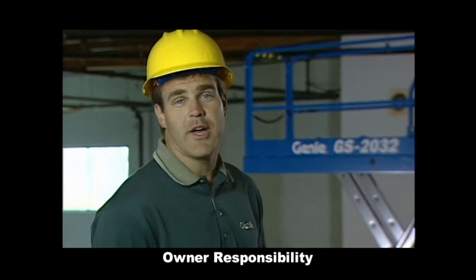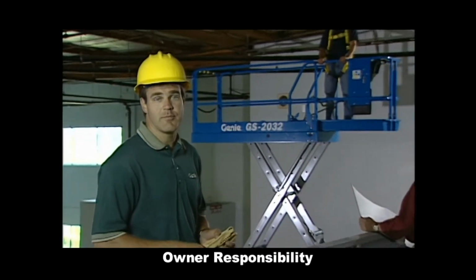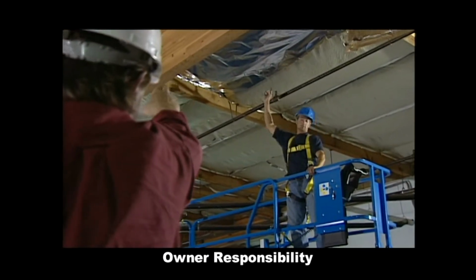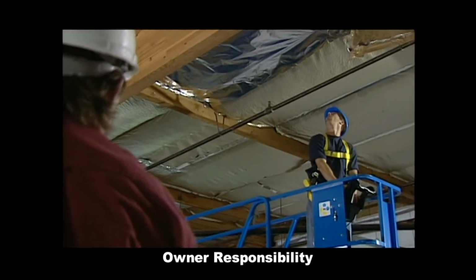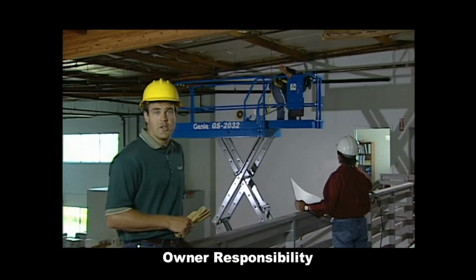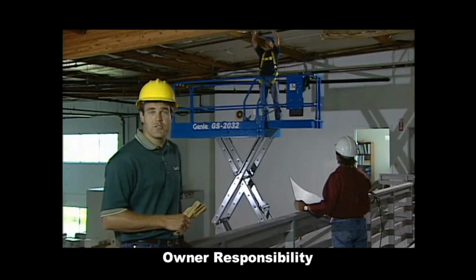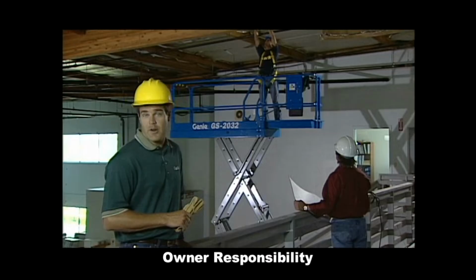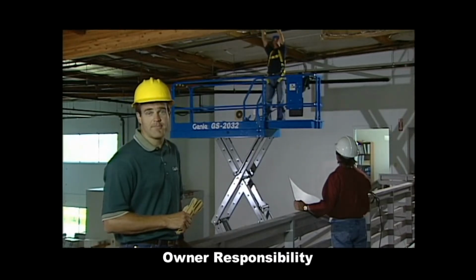The owner of an aerial platform could be the dealer in a rental situation or may have the responsibility of a user if they are directing operators to operate an aerial platform. Now, the user is someone we'll talk about in a moment. It is the owner's responsibility to make sure that the manufacturer's operator's manual is in good condition and stored on the machine. And just like a dealer, an owner must maintain the machine to manufacturer's specifications. Whenever an owner directs or authorizes someone to operate an aerial platform, the owner must provide appropriate training and familiarization.